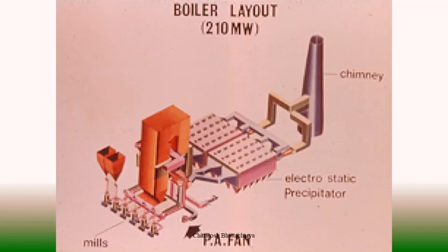So to prevent the ingress of coal dust which can contaminate the lubricating oil or gearbox oil, we have a constant supply of sealing air. This sealing air supply is either done by a seal air fan or, when a seal air fan is not available, we sometimes use a connection from the primary air supply system, the cold primary air supply system, and that is providing the sealing air for the purpose. So this way a primary air system is placed.